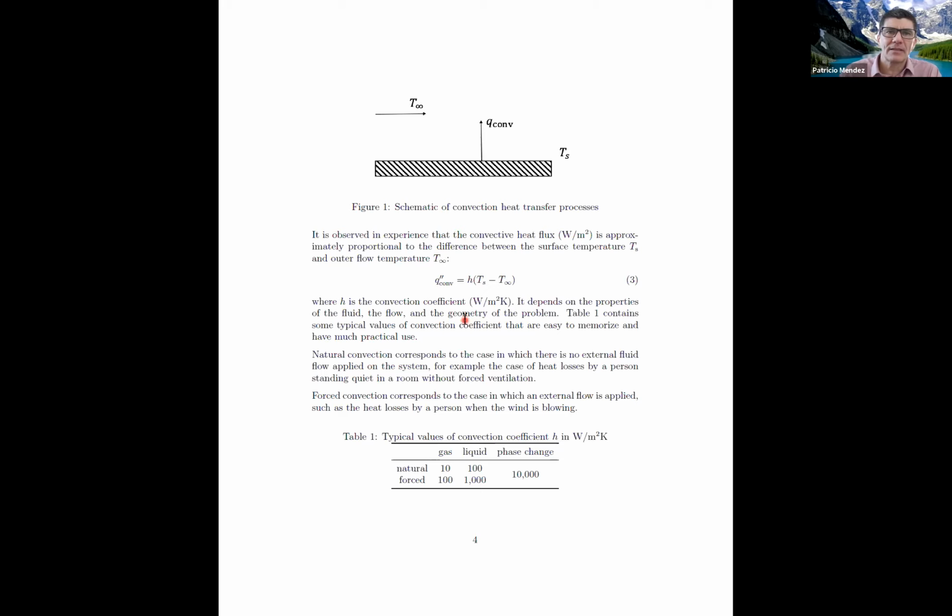Look, now this is kind of amazing because we have a formula that is ridiculously simple. All the complexity of advection and conduction and turbulence and buoyancy and material properties, crazy stuff, all goes inside h.